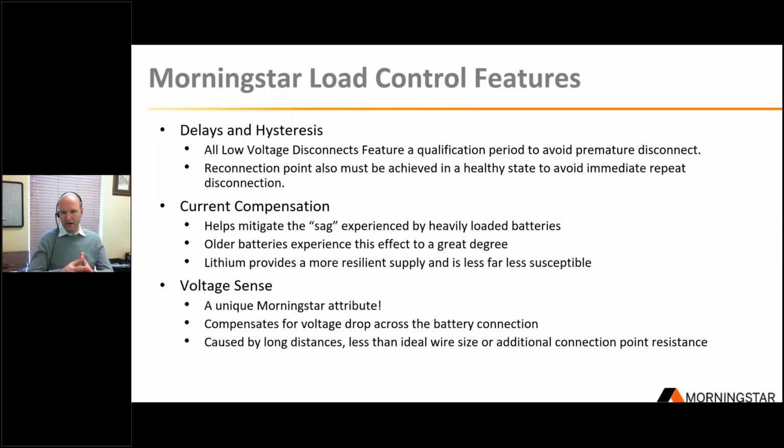And that's just something we encounter with a lot of industrial systems that are drawing a lot of current at a high DC rate. Older batteries, you'll tend to see that this kind of sag that occurs on older batteries is actually more pronounced as they get older. They dip lower, they bounce higher when they're under charge. They're not as stiff of a design as they were when they were brand new.